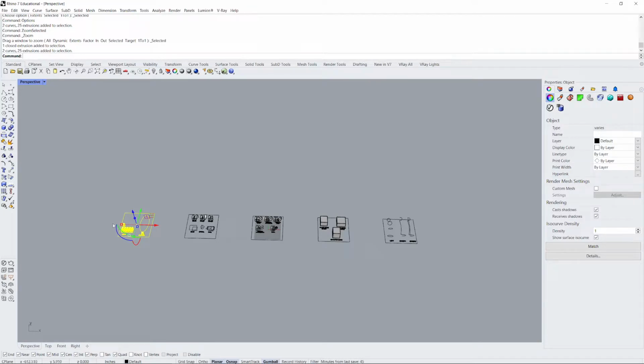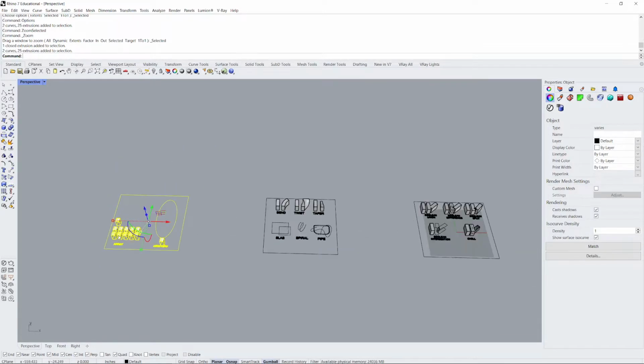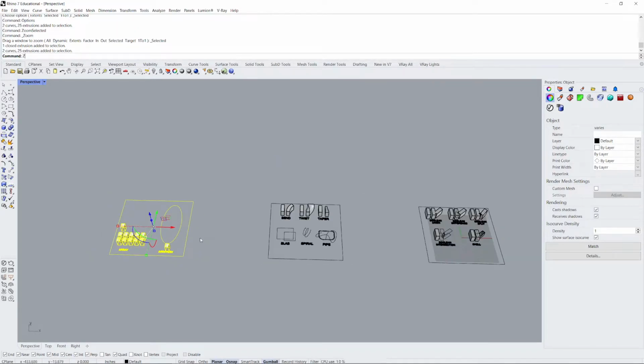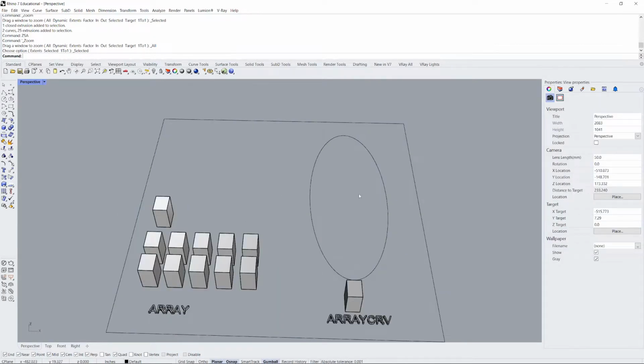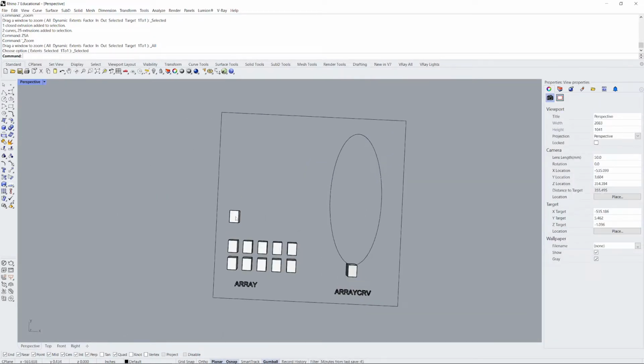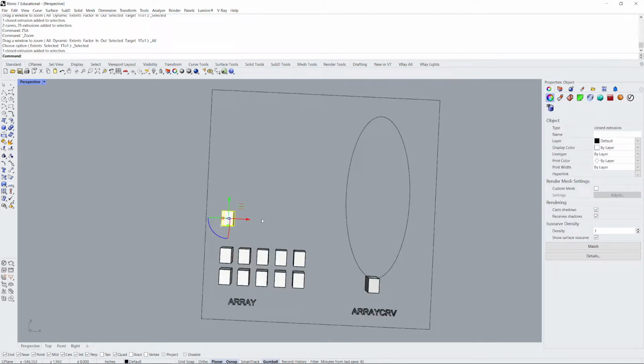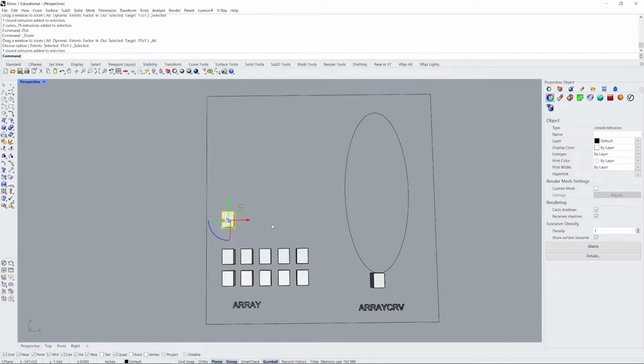As we get started, I did see some people struggling to zoom in and out on things. Sometimes the scroll wheel just doesn't do it. If you select something and you type ZSA, that'll take your screen right to it. So this isn't really a 3D command that I want to show you, but it is super useful and can be used on every type of object from curves to poly surfaces and everything in between.